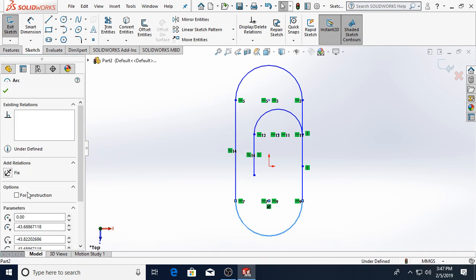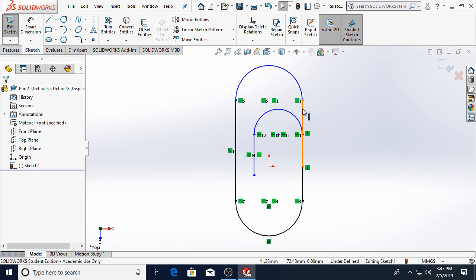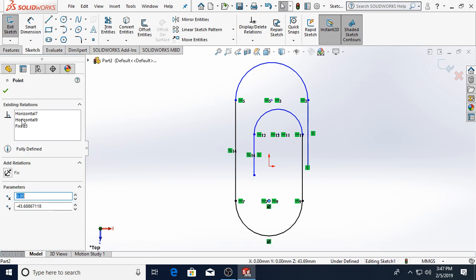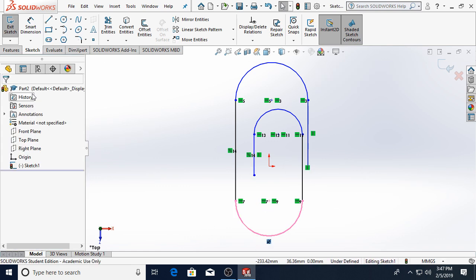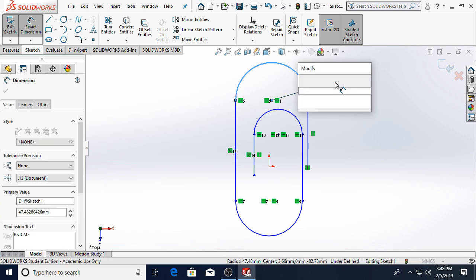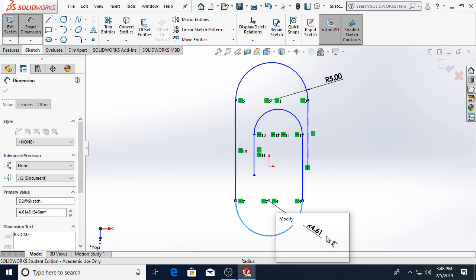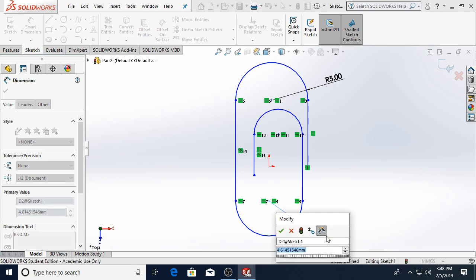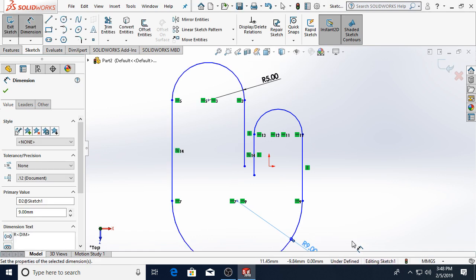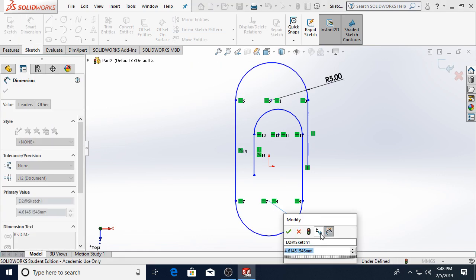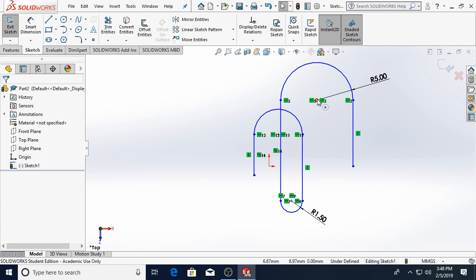this is just another example of a situation where troubleshooting is really the lesson we're trying to learn. Remember, again, we are going clearly way too fast for anyone to keep up, so that is an important thing to be aware of. Okay, now I can start dimensioning because I have the approximate shape established. I'm going to establish the top diameter as 10 millimeters, the bottom diameter as being 9 millimeters. Half a 9 would be the radius, so 4.5, or 9 divided by 2.